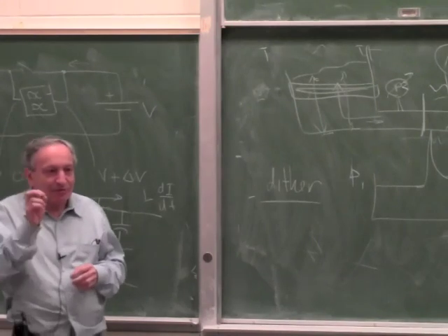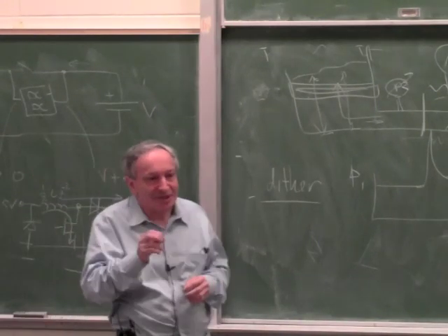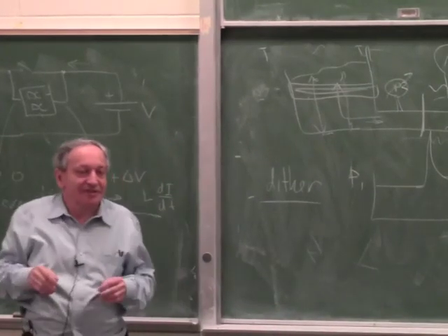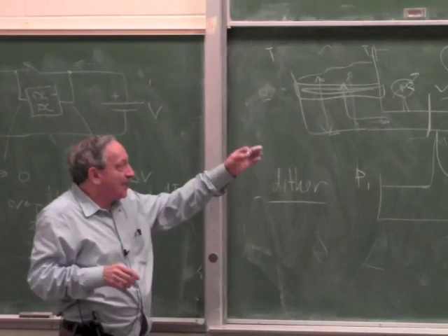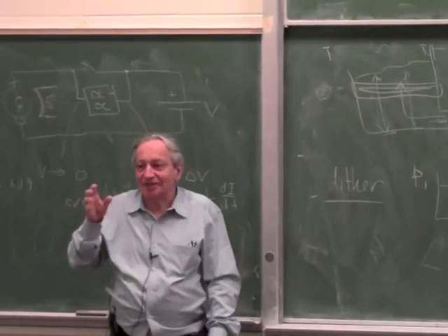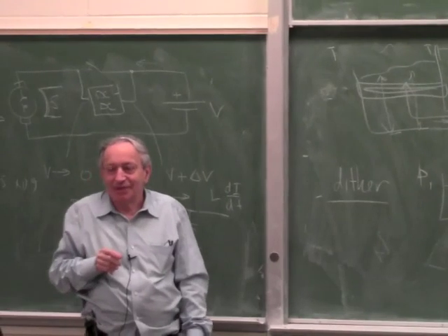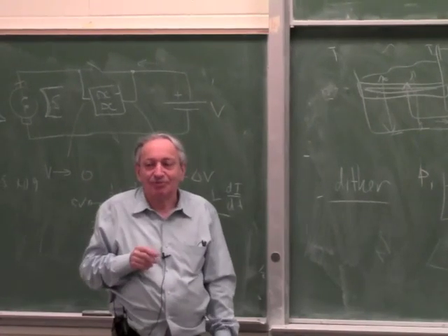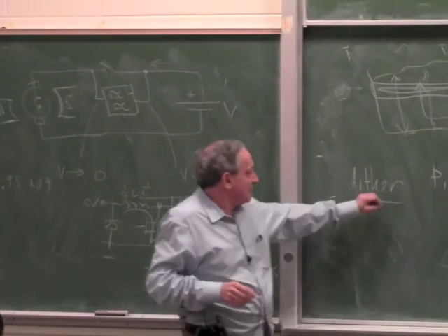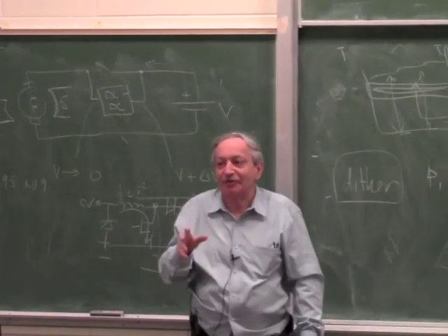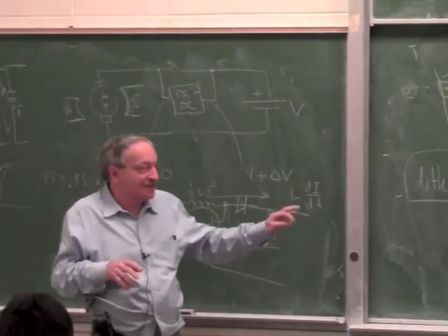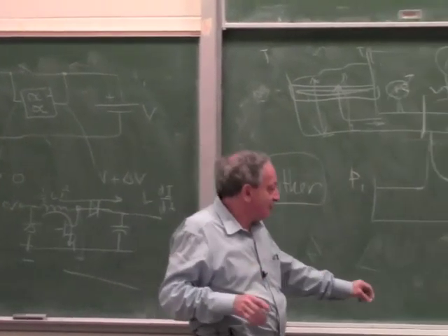But if you have a very small static error, and you do a double integration, this error will grow to infinity. So if you have some mechanical systems, you also introduce dither. You want to take out any static friction. But in hydraulic systems, it's almost impossible to do without it if you want a very high performance servo. So this is the only time where you'll see something equivalent to AC in a hydraulic servo. Anyway, that's just an example that a servo doesn't have to be electrical.